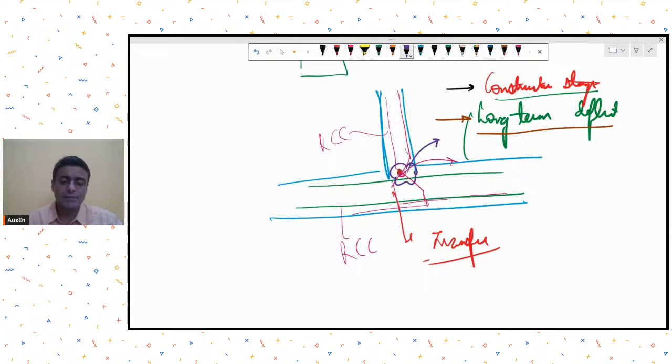If it's an RCC system, if it's a steel system, of course I can create a beautiful looking pin joint over here and I can proceed with the transfer girder design. But whatever you do about the end conditions for this floating column and transfer girder, I think the important design actions that you should remember are the long term deflection and the changes in the bending moment and shear force due to the construction stage. Okay, so I think you need to pay more attention to these issues.